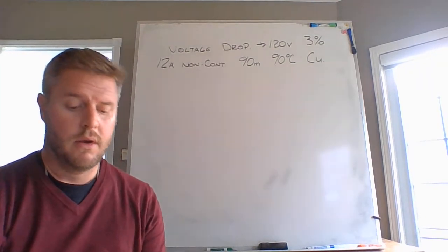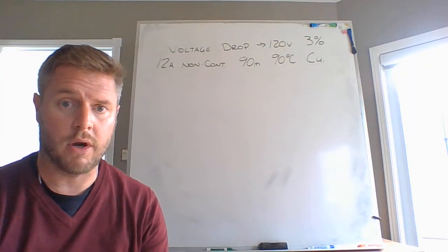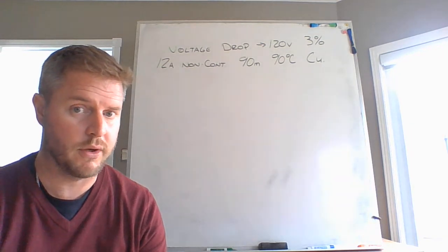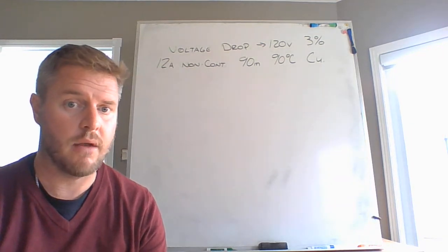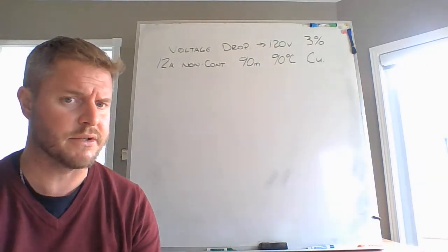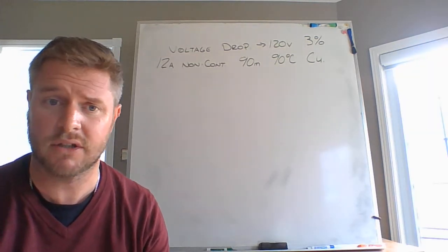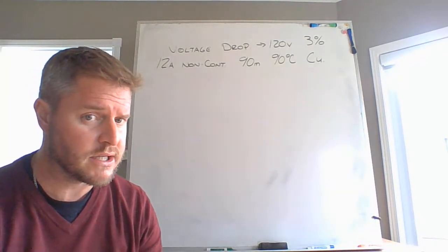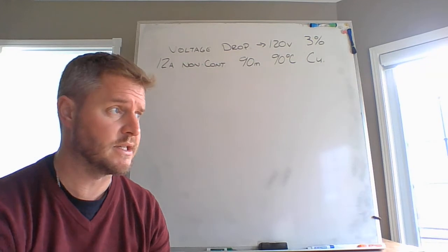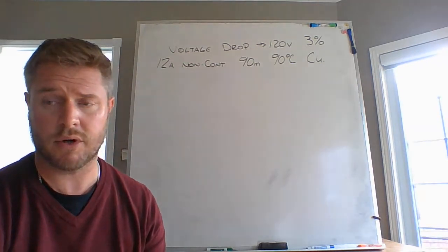Okay. Welcome back, guys. We're going to do a voltage drop calculation. Maybe the more common way of doing a voltage drop calculation is knowing your distance rather than your allowable distance, and you can run a specific gauge of conductor. You do not need to memorize these calculations. These values are available for you in Appendix D in your code book, where we're about to go.